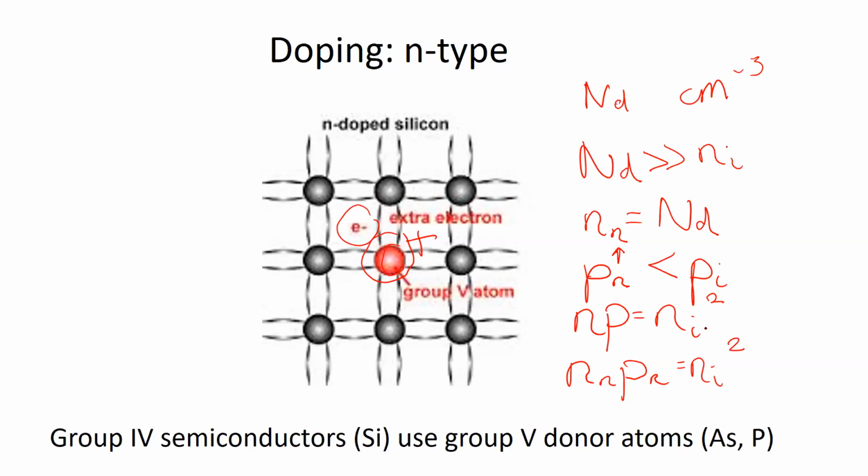It still remains constant. So this means that if we know the doping concentration, which we do because we set it as a design parameter, then we can calculate the number of conducting electrons and conducting holes in order to calculate the current, since ni is a constant for a given material. And we're going to see and use this throughout the course.